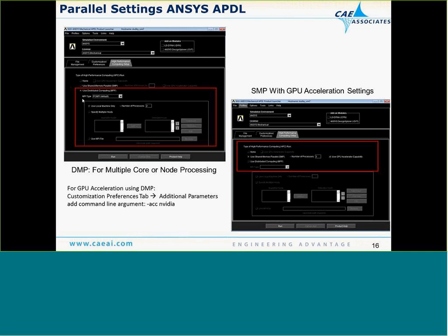If you wanted to run distributed across multiple hosts, it's simply down here where you see me moving my mouse around, we can add the different hosts, the different nodes, and select them to our list, and then simply specify the number of processors that we want to run across those hosts. Now, that's not the number of processors per host, it's the total number of processors.